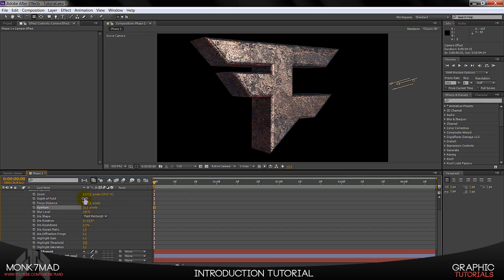So we're going to make sure that the depth of field is switched on for starters, and you might see that the document automatically blurs. Now, that's great because we know that the depth of field is on, but how do we fix the blurring issue? Well, what we need to do is play around with the focus distance, and this is exactly like if you were using a proper camera. When focusing on an item up close, you need to make the focus distance closer, so a smaller number, and the further away you're focusing, the further away the distance.